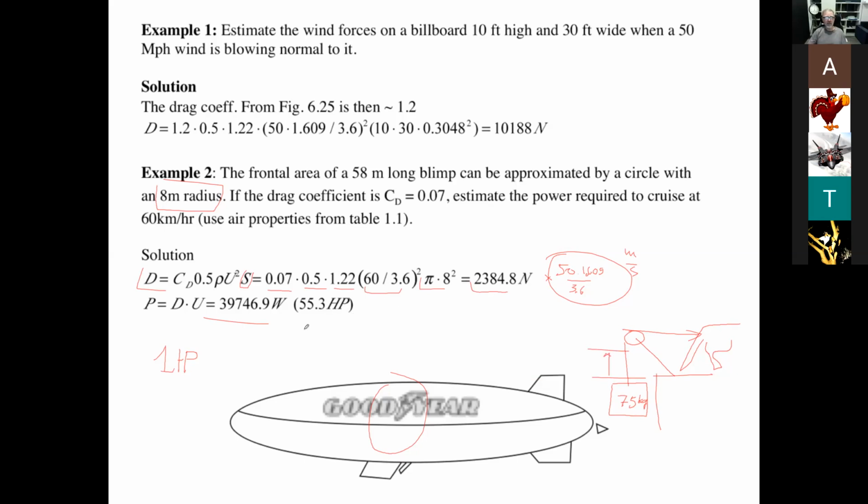So it's 75 times g, 9.8, and then multiplied by 1 meter, that's the distance, per second, so it's watts. It's something like 735 watts or something like that. You divide that and you end up with 1 horsepower, okay? Today we don't have too many cars with 55 horsepower, but some of the older cars will have 55 horsepower. That's good enough, okay?